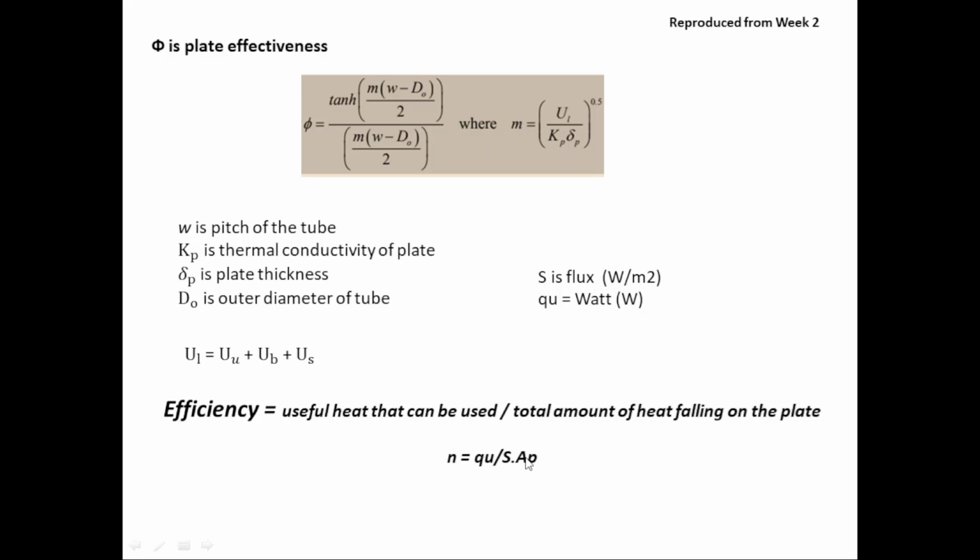So in case of the flat plate collector, since it's a non-concentrating collector, your absorber area as well as your plate area will both be the same, as there is no kind of concentrator involved. So let us actually move towards solving the problem.